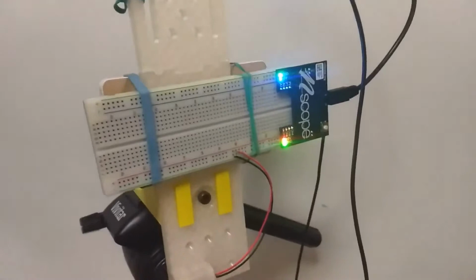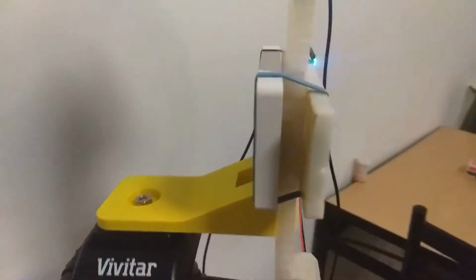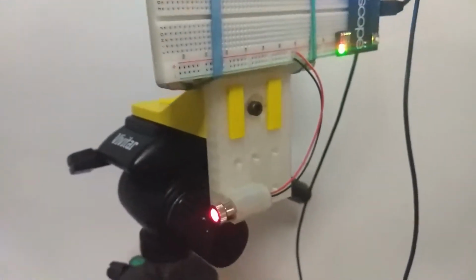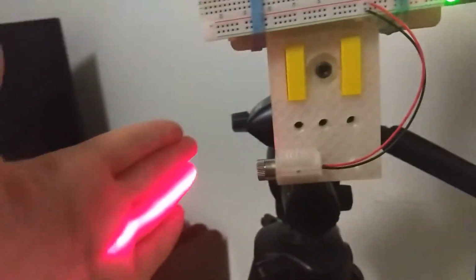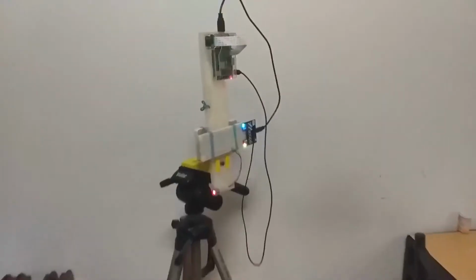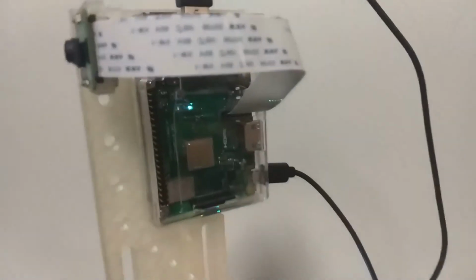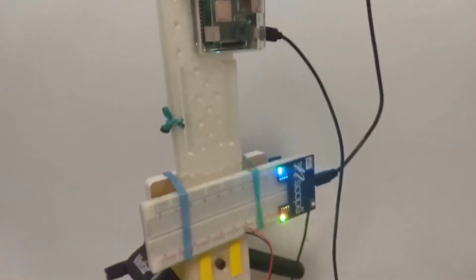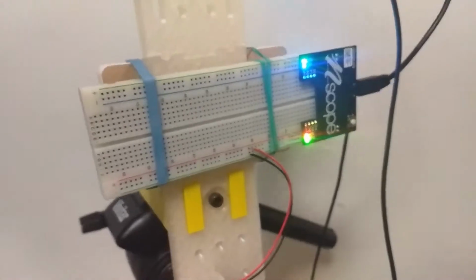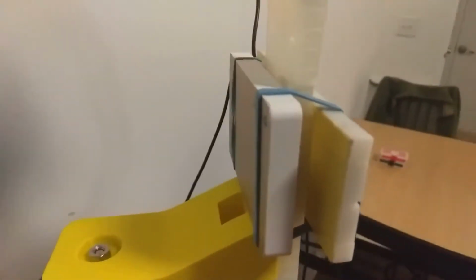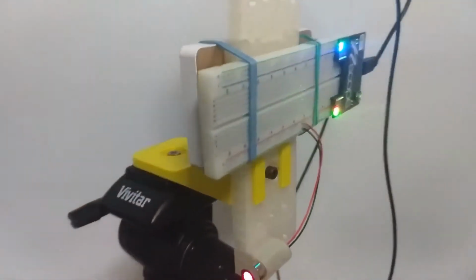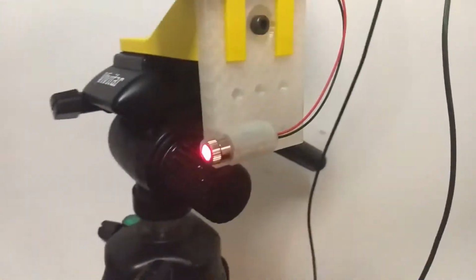As such, 2 key elements are the transmitter and the receiver. Generally, the LiDAR emits a laser pulse from the transmitter and detects the return with a receiver. The time it takes for a pulse to return to the receiver, along with the speed of light, is used to calculate the distance of a target. In my system, the transmitter is the red 5-volt line laser, and the receiver is an 8-megapixel Pi camera.